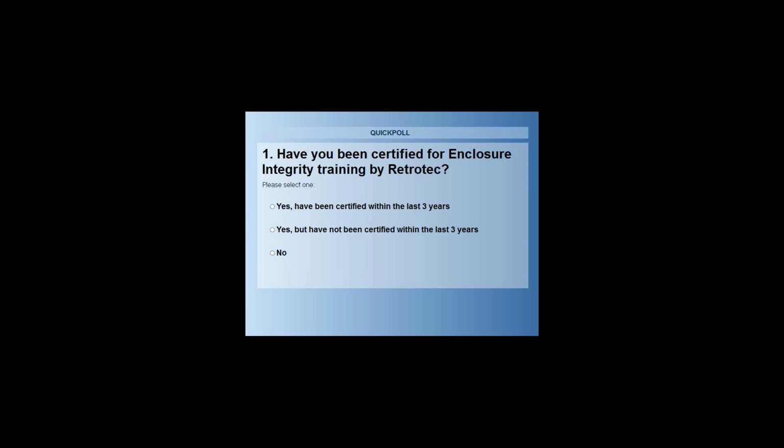So let's take a look at the first slide that we have here, which is on what we call a door fan test. The door fan test has essentially replaced the discharge test almost universally, starting, as I said, in 1986, and I think that we have a pretty high level of door fan testing as opposed to discharge testing going on. There's the occasional time when a discharge test might be performed, but by and large the door fan test does that. Even if you are going to do a discharge test, it allows you to determine whether or not it will pass the discharge test.